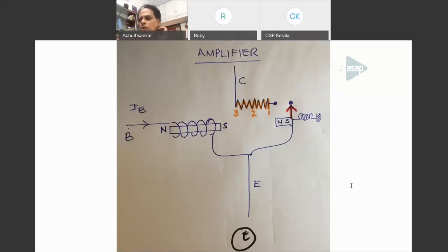Now, what is the solution to this? The solution is very famous. It is known to all transistor engineers. The solution is called biasing. You give a small voltage to the base always. It is a DC voltage. It is fixed to the base always. And on top of it, you give an AC signal.